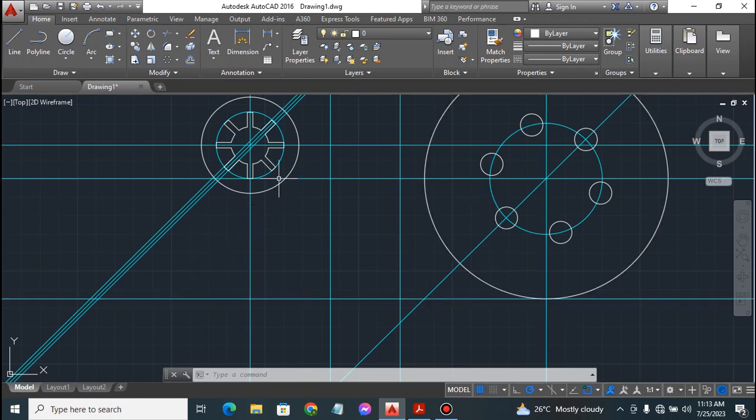So we'll go to the drawing board, click the line tool. We're already on the current layer, so you click the line tool, then we'll locate the tangent point of this circle. As you can see, once I place my cursor above this large circle, you see this circular indication giving us tangent points on the larger circle. I'll select any of the tangent points right here. Now drag the line straight up to this point of intersection of this construction line. That's where the line is going to end for now.